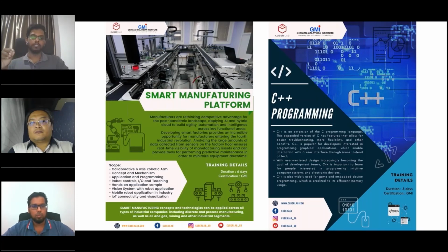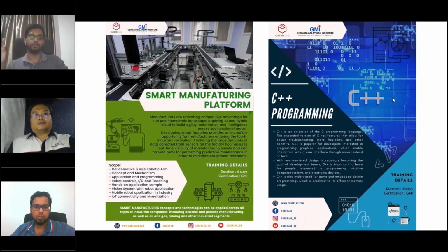Because when you put a vision on the tool itself, there are some advantages and disadvantages. For example, if you want a good cycle time and you mount the vision on the robot, you have to take a picture and process it before picking the part. But if you put a stationary vision while the robot is moving, another picture is taken and the decision has already been made. So it increases your cycle time output. The decision on what kind of vision application depends on your process, and then we make the decision accordingly.